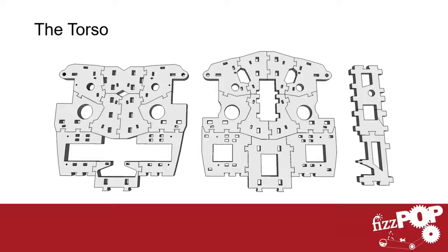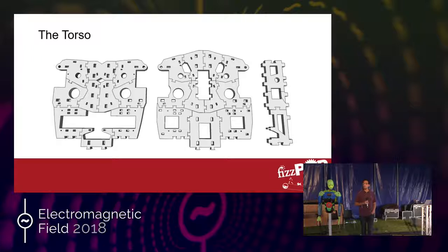So as I said, laser cut all the flat parts. Now, if I am to rebuild the robot again, there are flat parts in the arms that I will also laser cut rather than 3D print. So ideally, any flat part, you could just laser cut quickly. I laser cut mine from a combination of MDF and acrylic. It should be a 10 millimeter thick part, so I cut it from 6 millimeter MDF and 4 millimeter acrylic, only because that's what I had. I'm not saying that this is the best way to do it. Ideally, maybe you should just cut it from one sheet of material if you have a laser cutter powerful enough to cut through 10 millimeter.